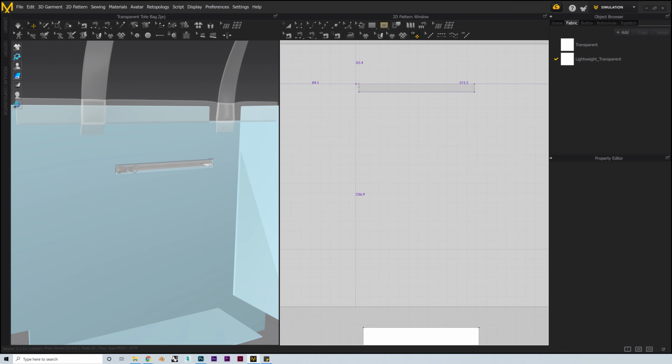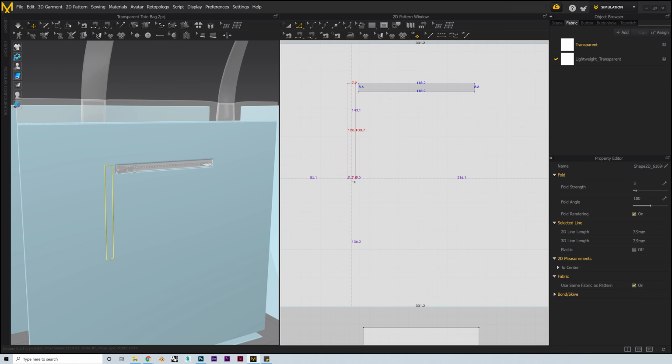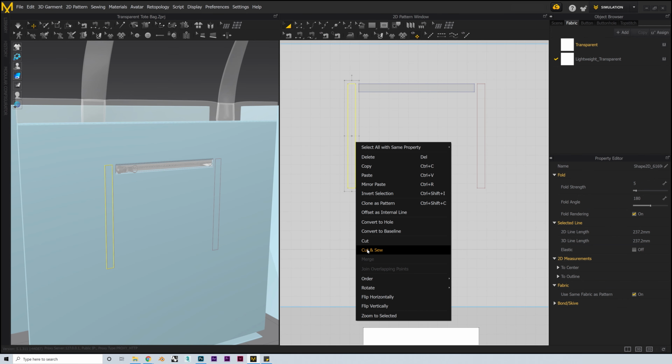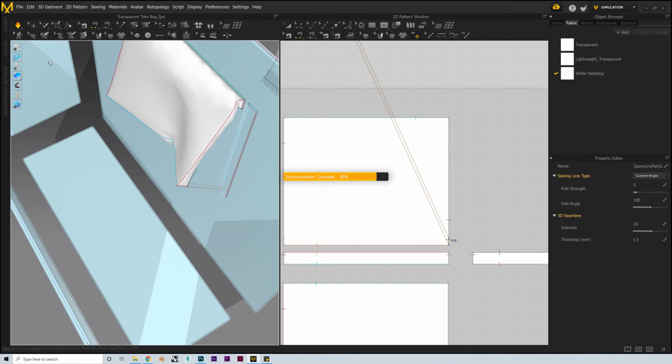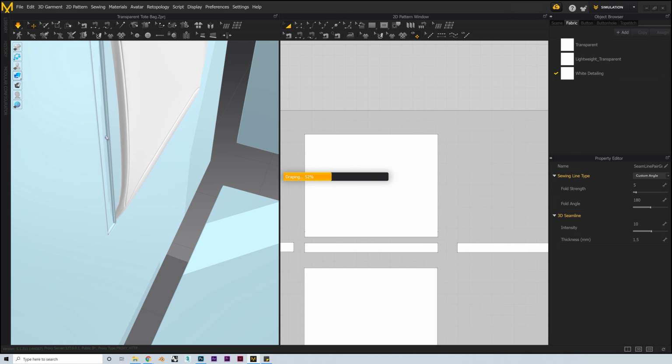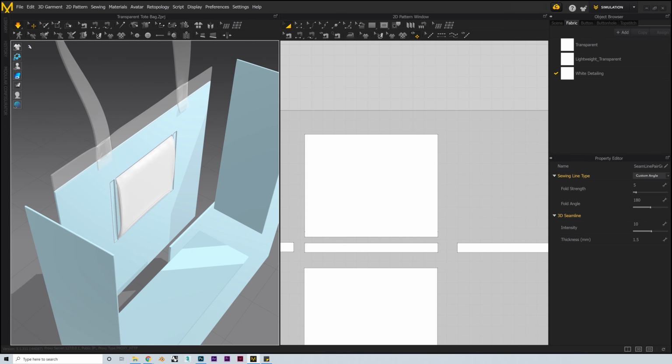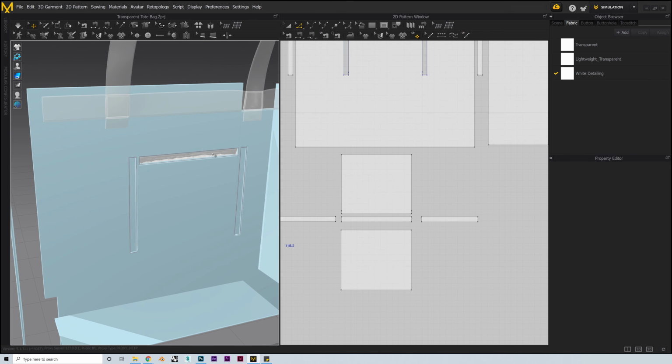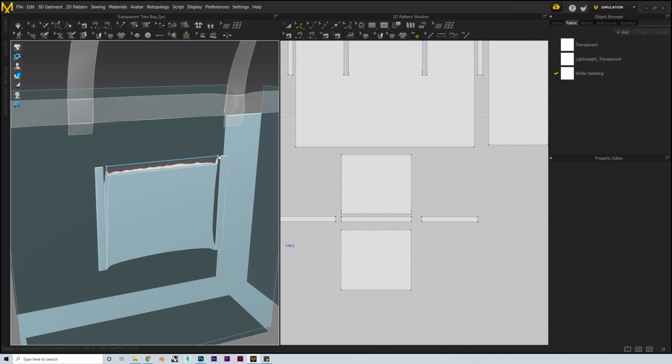We can then add in some side seams for our pocket by adding in a couple of internal rectangles to the main body of our bag before sewing the sides of the pocket to the inside edges. Then finally, we'll add in a zip using the zipper tool, first going over our top line before then double clicking and going over our bottom line.